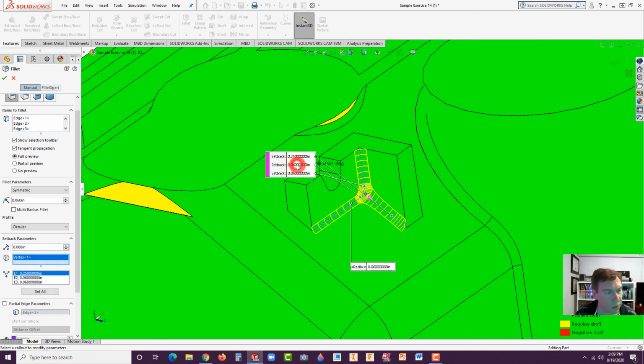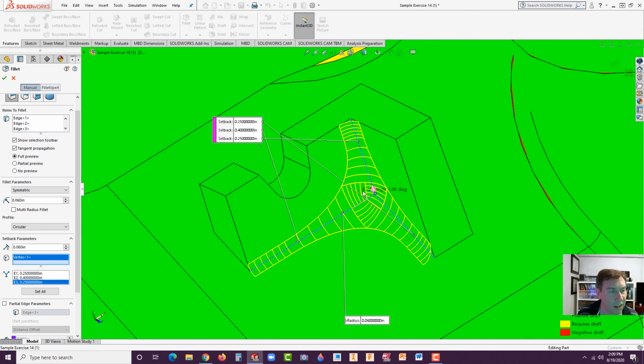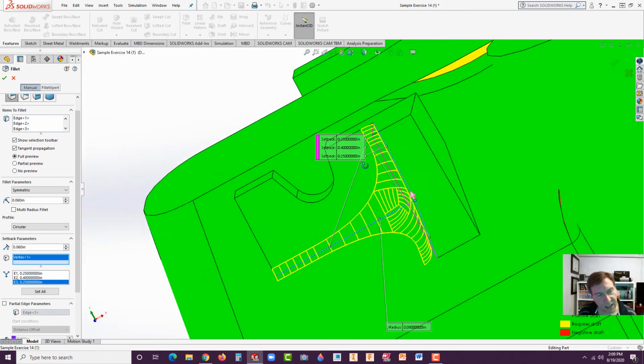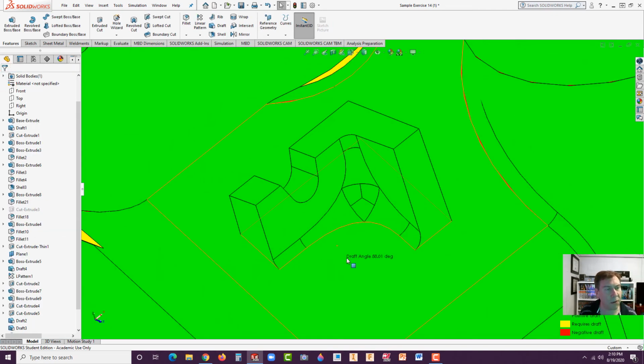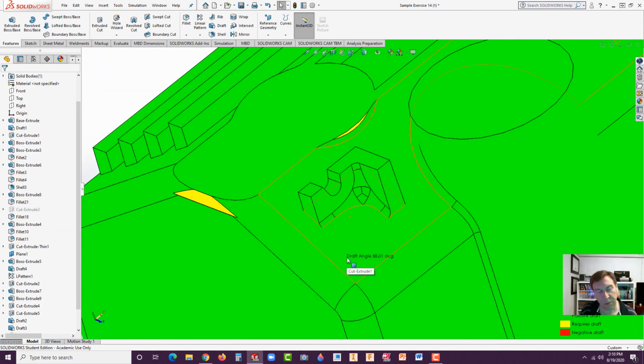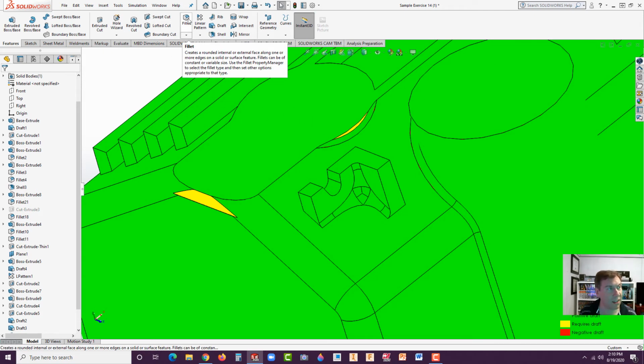Okay, double click on the next one. And this one, mine is showing the long edge. So this is going to be 0.4. Now, mind you, if you don't get them right, you'll get a little error message here. Now, the next one going vertical, that one's going to be 0.25. Now, look at what it's creating. I told you, it's kind of like a spider web almost. It's adding a thickened approach there, and hit the green check. And that's going to help prevent a cracking effect. All right, so setback fillet, neat fillet to use.